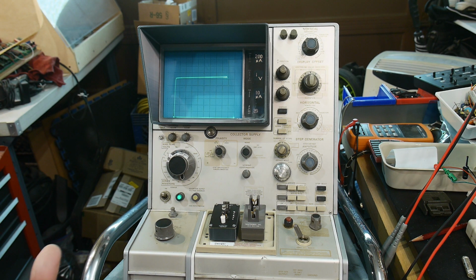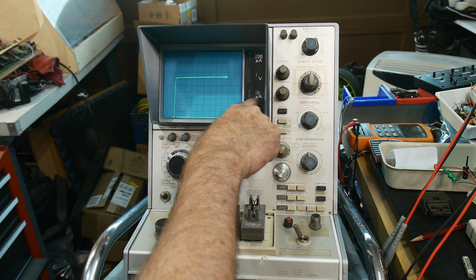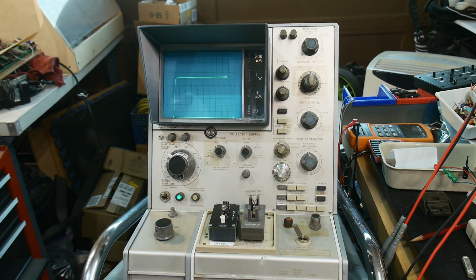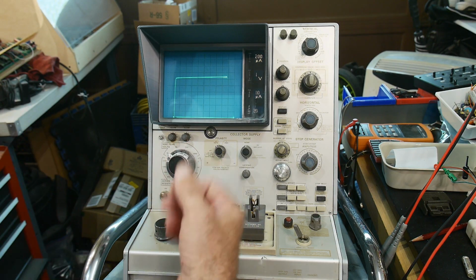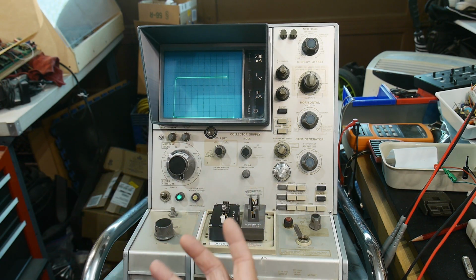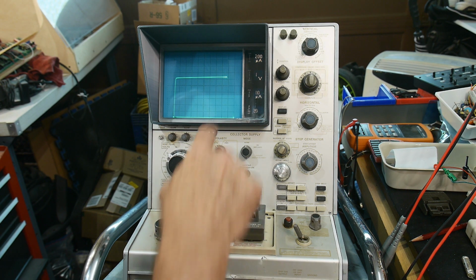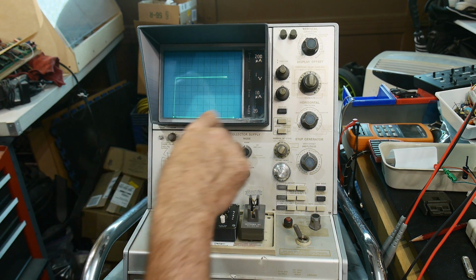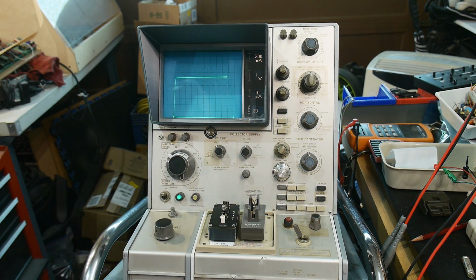Remember, transistors multiply gain. You put in a little bit of current and you end up getting a lot of current out. And the ratio of how much output current you have to how much input current you have, that is the beta of a transistor, okay? And right here it tells us that we can also read the beta right off of the vertical thing. It's 20, beta of 20 per division.